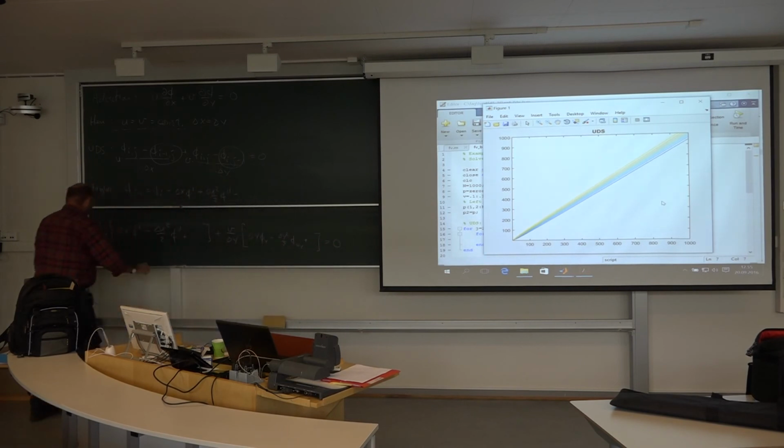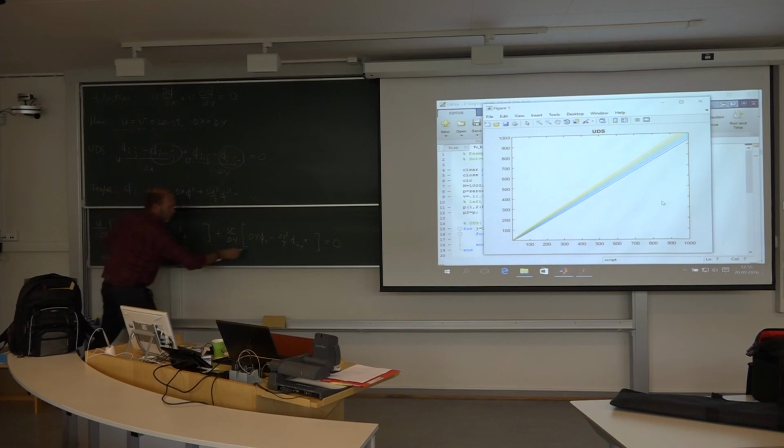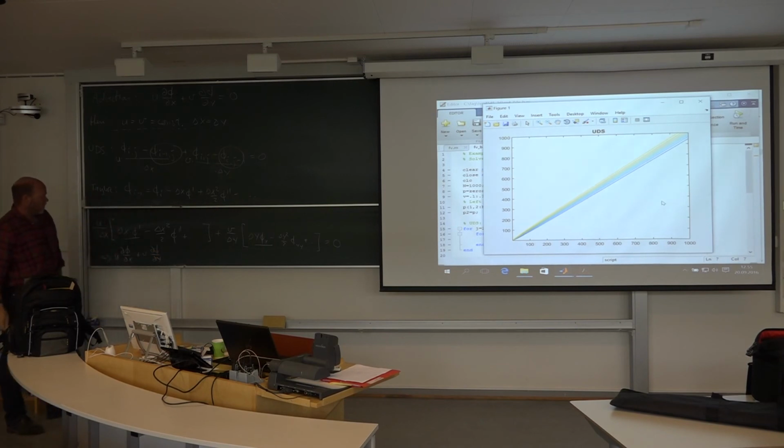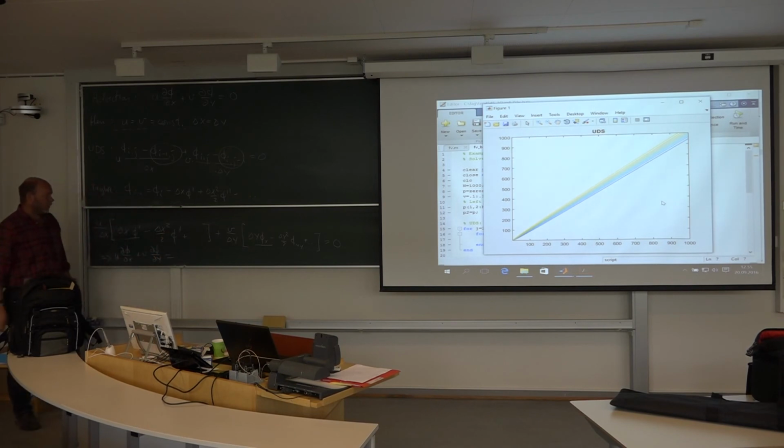So what will you get from the modified equation? Here you will have the first order derivative with respect to x, multiplied with u. So you will have u dphi/dx from this guy. From this one, you will now have v dphi/dy. And this is very promising. We get back our original equation, as we should. Then we have some other terms. I throw them on the other side.